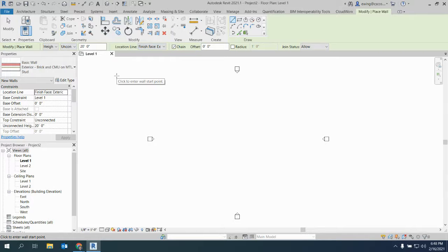If you walk up to this building, hook your tape measure onto the brick face, and drag it down, you're measuring the outside face of that building. So these are the constraints we want to hold. In Revit, most of the time you're not going to know exactly the wall system that will be there when you start modeling. But if you do change the thickness, you know which direction it's going to go. So we want to hold that location line to the finish face exterior.